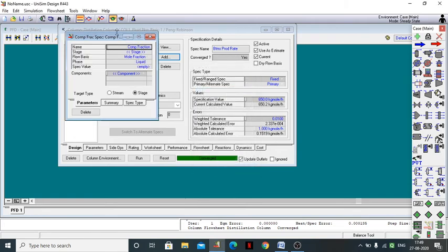Now that is highlighted here, right? Now we have to find the composition of the distillate, so it is not a stage, it is a stream. So select the stream button, and under the draw condition you will select distillate column. For basis we have given mass fraction, so select mass fraction, and the spec value is 0.8. Now we have to select the component, so we select the component benzene in distillate, right? Now we have made the changes.